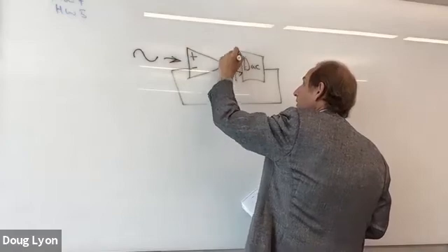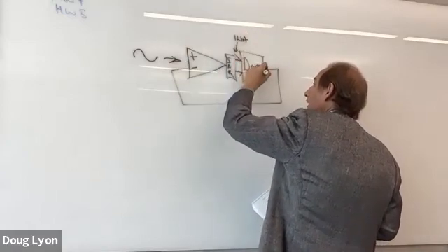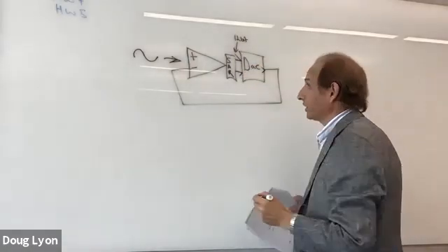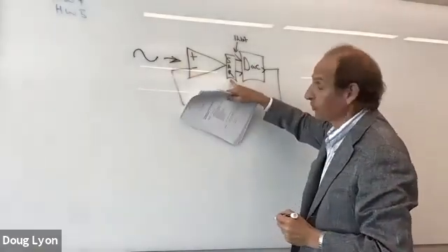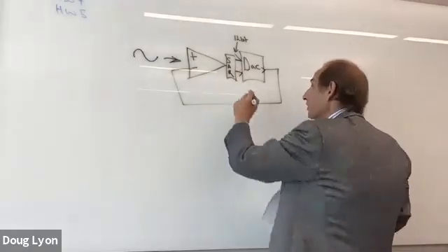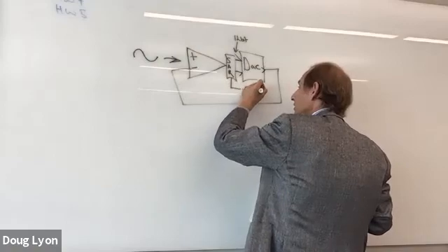And so this could be 12 bits going into our little DAC. Here's our little output from the DAC. And when the DAC is chasing after this input signal, the successive approximation register has to be counting up or down. So it needs to have its own little clock. It's an up-down counter.